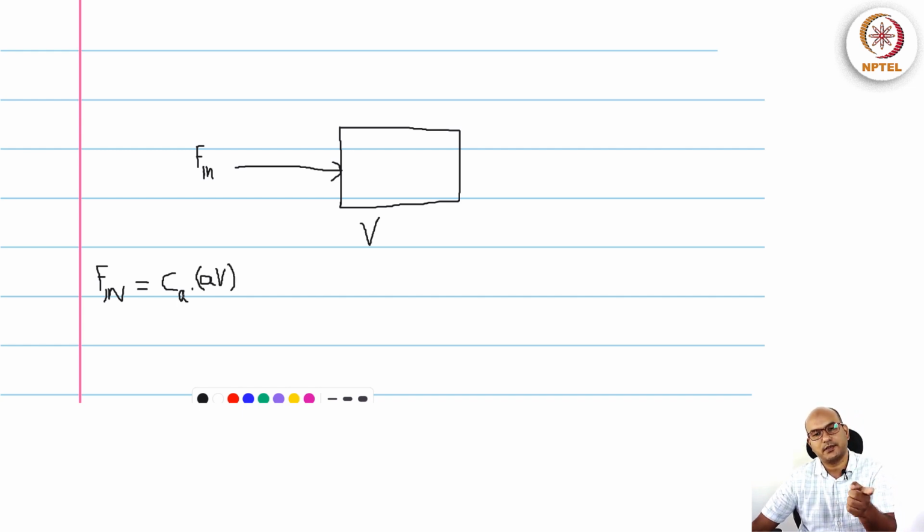So concentration, air exchange, additionally this much volume is coming. Additionally we will have a penetration efficiency, because not all the particles or not all the pollutants are coming in. So we have F in, then we have a decay at rate constant K. So decay would be, let's say, reaction loss would be K times M.